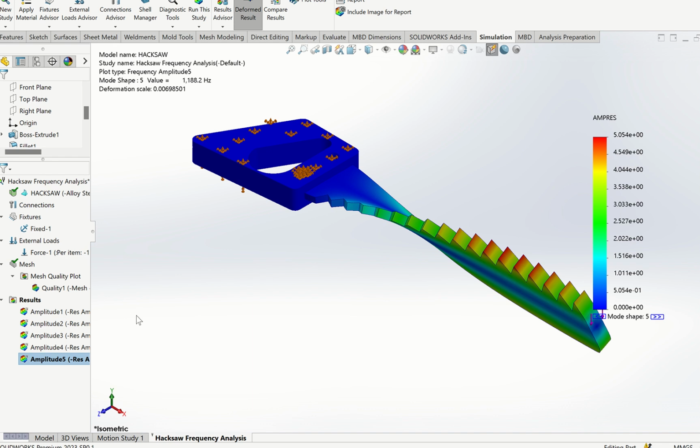And what we covered in our basic introduction was vibration analysis, and we said there are various types of vibration analysis. But the first one we have done is frequency analysis, to visualize the various mode shapes, and also to visualize the fundamental frequency, and how the system fails, where we have the natural frequency and resonance, where you excite the system at various points when it vibrates.